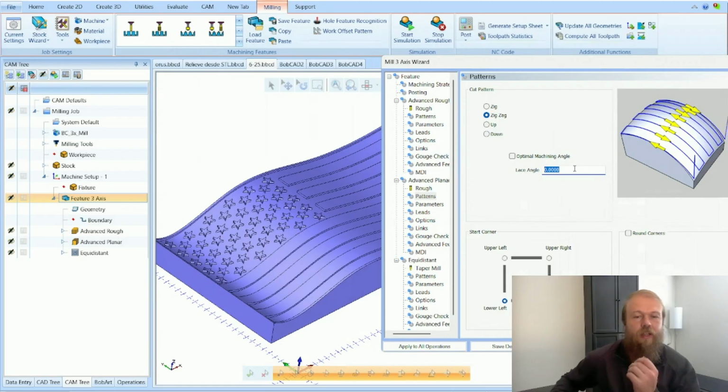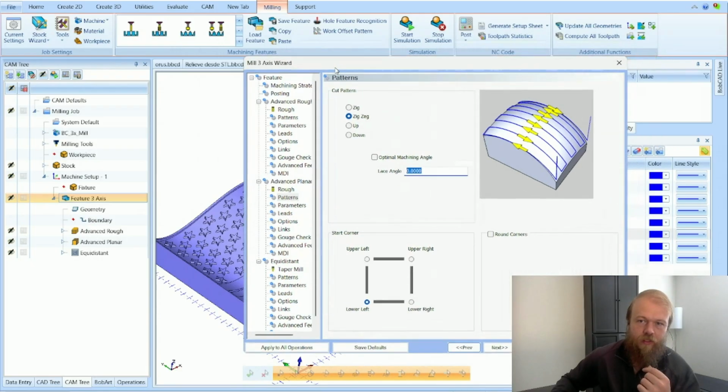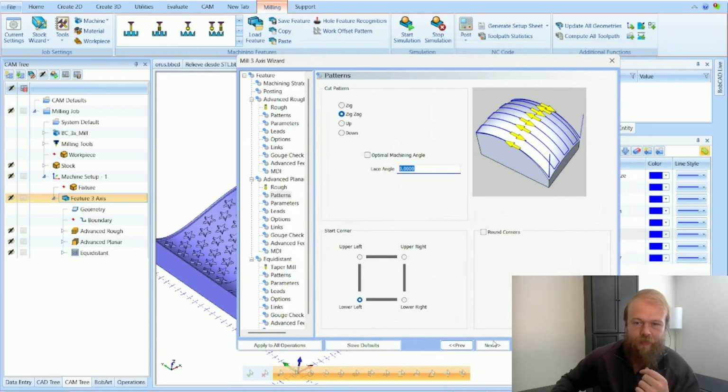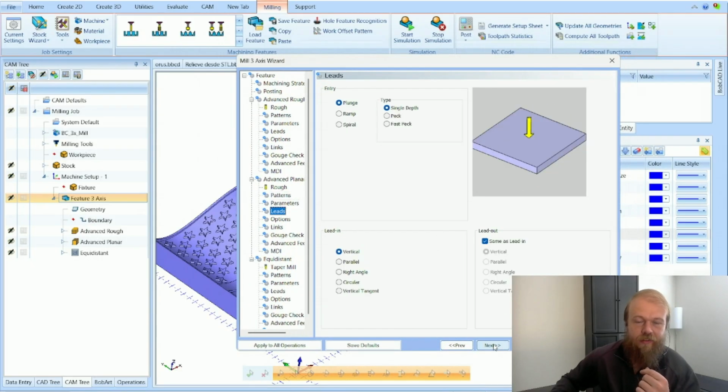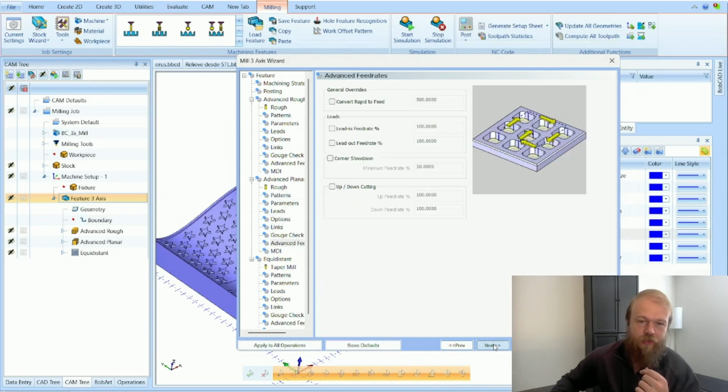So sometimes, especially with woodworking, you could do 0 degrees run across the x-axis, and then you could do another planar toolpath at 45 degrees, and it'll cut in a different direction so that it goes sort of against the grain from the original 0-degree angle. Give you a much better finish that way. Other than that, I left everything by default for the planar toolpath.